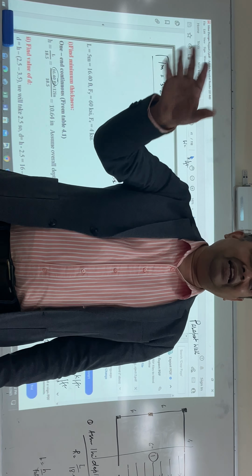Practically it is not happening. But you cannot prevent it if the users say everybody wants to go at one time. You cannot say this slab is not designed for that. So that is why you are designing for a severe loading, for the maximum loading, so that anything can happen and it will not be damaged.